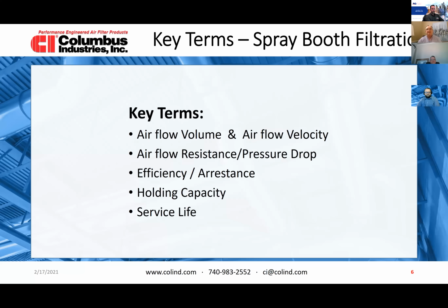The holding capacity is the loading of the filter. If the filter is completely not closed or not efficient at all, it will not hold any particles. So sometimes you'd hear a filter lasted forever, but it didn't stop anything. But for a filter that has efficiency or arrestance, as we mentioned here, it's going to have some holding capacity. And we use the word capacity because at one time, it's going to stop taking those particles. It's going to stop receiving.